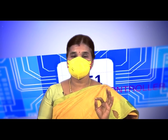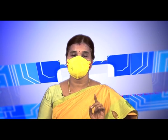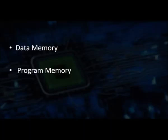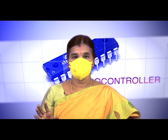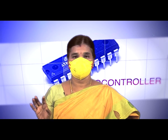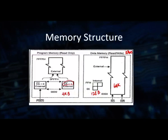That read bar signal is connected in the 8051 to PSEN, which is the program store enable signal. The 8051 memory is basically divided into data memory and program memory. The data memory is nothing but the RAM, which is read and write. The second one is program memory, also called code memory, because the important codes will be loaded in this memory. It is a ROM, read-only memory, where only the read operation will be performed.